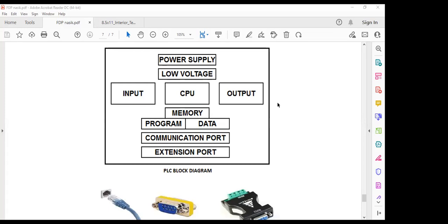And as other people told, some sensors we can use, like we can use a proximity sensor also on the shaft. We can put some metal and put one proximity metal detector. As it rotates, for each rotation, it will be on. That will also be high frequency because the motor is running with speed. So this sensor will be on and off very frequently. So pulses will be generated, and they won't be taken by a relay. Okay, I go for the next example.